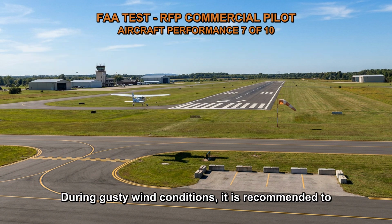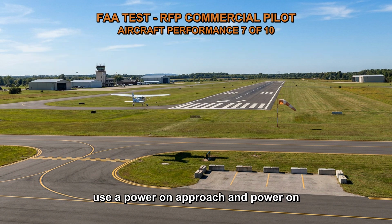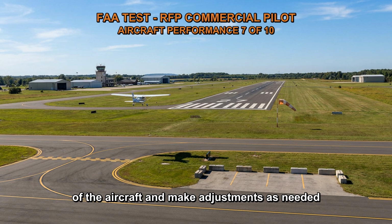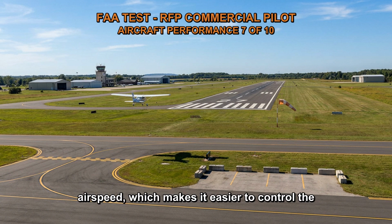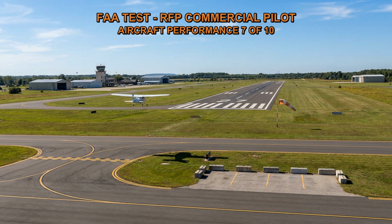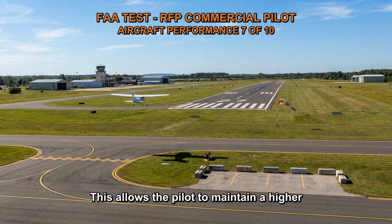During gusty wind conditions, it is recommended to use a power-on approach and power-on landing. This will allow the pilot to maintain control of the aircraft and make adjustments as needed to compensate for the gusts. A power-on approach is one in which the engine is at a higher power setting than it would be for a normal approach. This allows the pilot to maintain a higher airspeed, which makes it easier to control the aircraft in gusty conditions. A power-on landing is one in which the engine is at a higher power setting than it would be for a normal landing. This allows the pilot to maintain a higher airspeed as they touch down, which helps to cushion the landing and prevent the aircraft from bouncing.